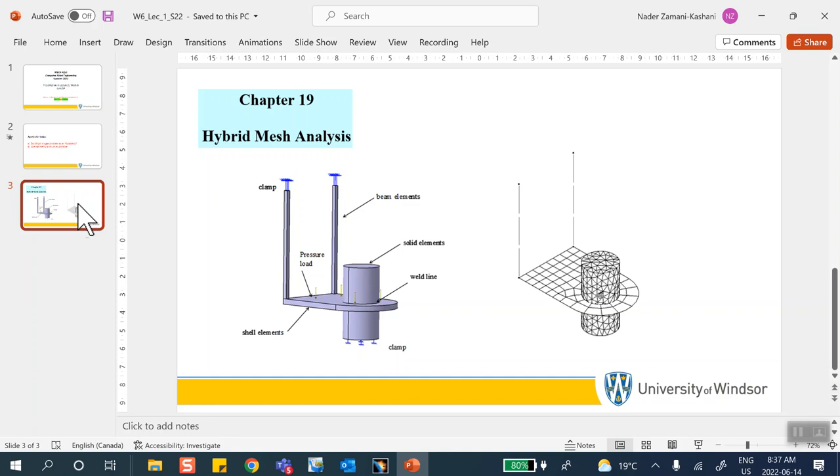Okay. So when I look at this, I do it the way I told you: I'm going to make a hole inside of that sheet and then put the cylinder in it and do the rest. Now, you also have the option of making everything exactly like it is, and then trying to cut it with the split that you see in the assembly design.